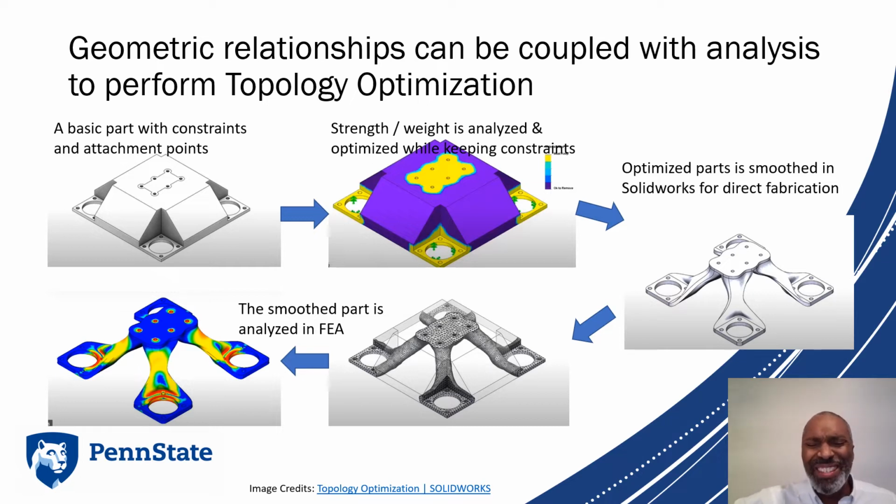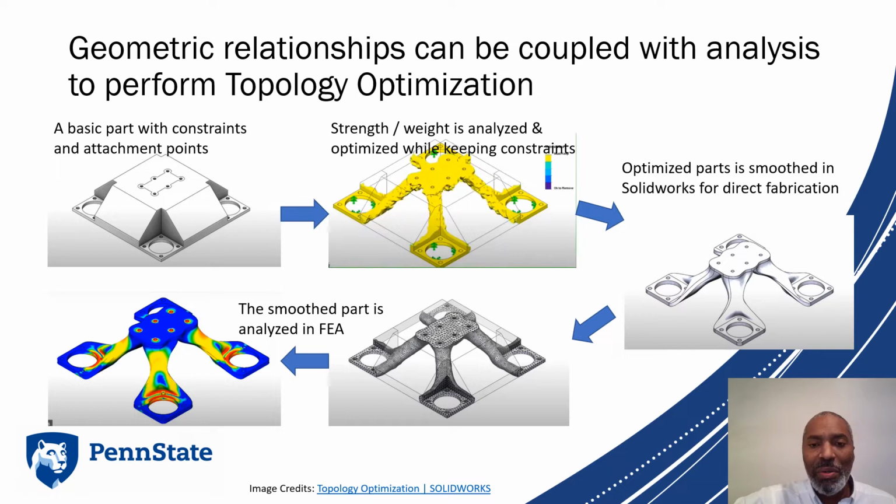What happens if the software does this for us? It performs many, many FEA simulations, trial and error, but guided by algorithms, and over time, it reduces the part down to what's left that you see here. In the FEA sense, all of those rugged surfaces are just discretized elements. Hopefully you know what that means if you've done one of the past tutorials of the FEA model. And the solution then is what's left here. Supposedly it has a higher strength-to-weight ratio and meets required strength considerations. And as you can see, those points that we were not allowed to change are still intact.